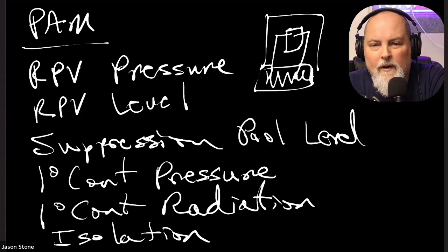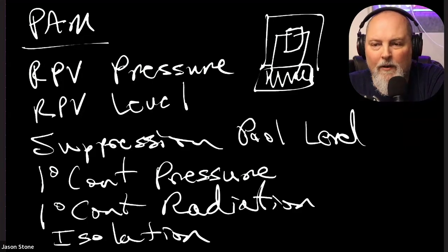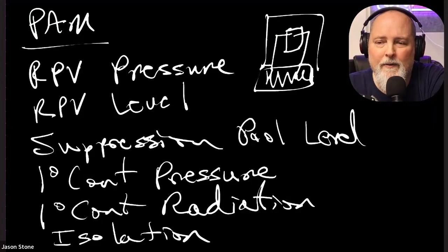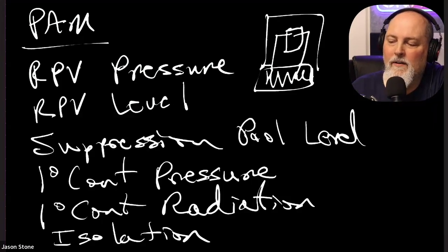And we want to see, did our main steam isolation valves close? What other valves closed? What other things closed that stop radiation or steam or liquid from getting into spaces we don't want it to get into? And ultimately, that all goes back to fission products. If we're experiencing fuel damage, all these things are carrying fission products with them, and it's being released from one barrier to the next barrier to the next barrier, and eventually primary containment, secondary containment, and then to the people space. So we don't want that to happen.